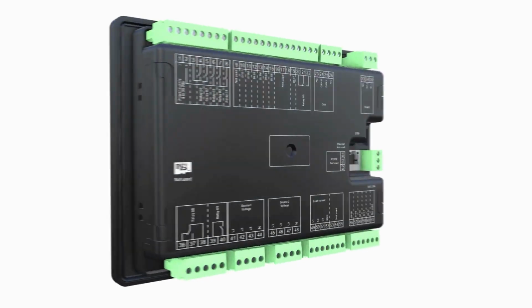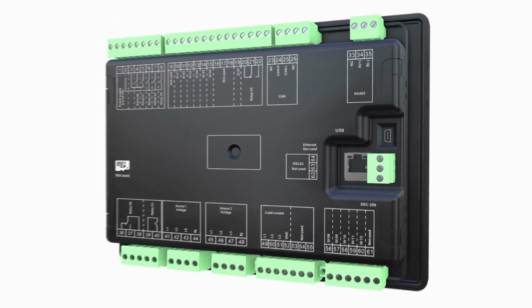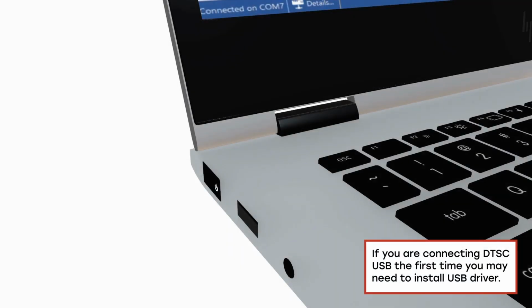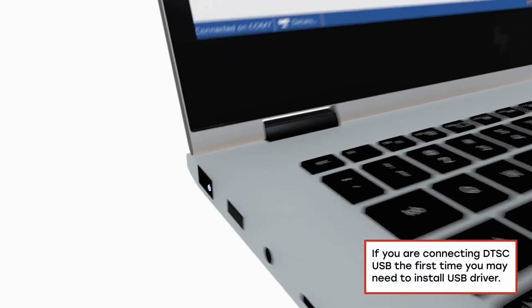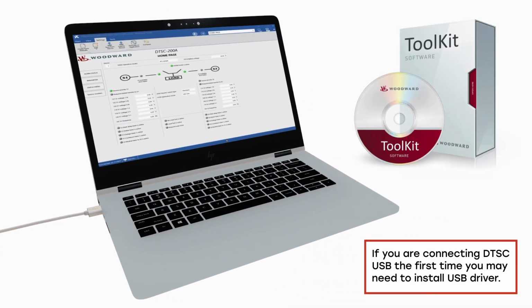Once you have both ToolKit and the configuration files, you can connect the DTSC-200A to your computer. Make sure to connect the device before launching ToolKit. Otherwise, ToolKit may not detect the controller. To establish the connection, use a mini USB cable.